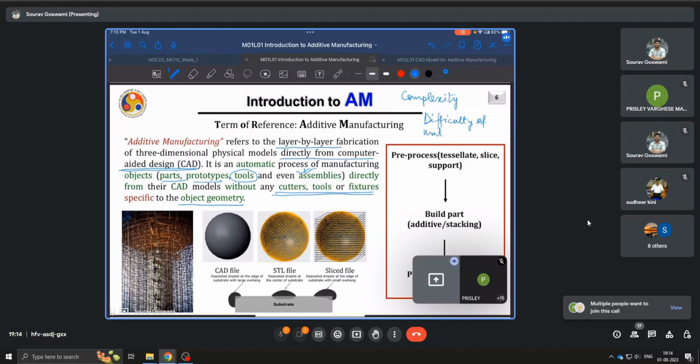For example, superalloys such as Inconel are notoriously hard to machine, but to deposit them via additive manufacturing is far, far easier. You can print the most complex geometry with Inconel and you'll have your part. This is where AM actually takes the cake and is superior to most conventional manufacturing processes.